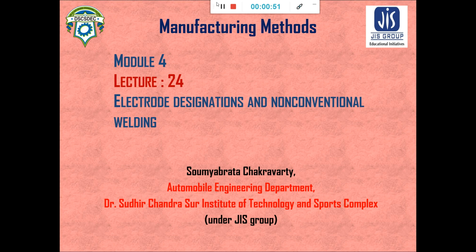So what is non-conventional welding? These are a special type of fusion welding, where we do not directly use the already discussed processes or the conventional ways of welding. Instead, the heat for melting is given in some other manner, for example by using a laser, an electron beam, heated high melting point slag, or hot gas. All of these non-conventional welding processes we will be seeing.